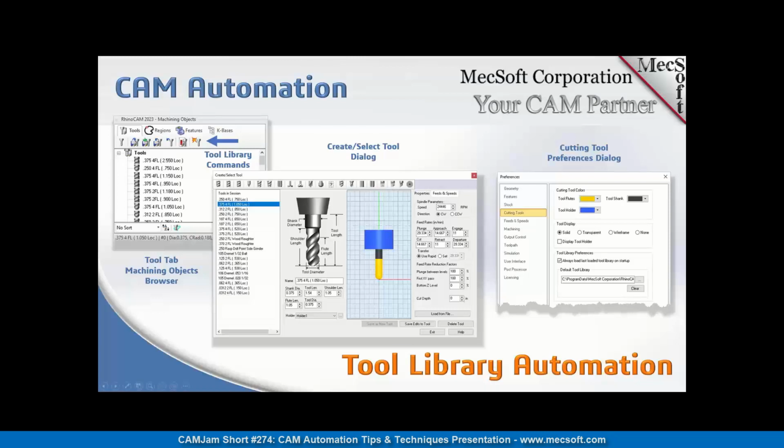When you define your tool, you're obviously going to set your tool dimensions, and you can set your feeds and speeds and the properties of the tool and some other options here. This knowledge gets saved with that tool based on the tool name. So you can embed all this knowledge that you need for a certain tool, and then you can carry that knowledge over into your operations when you load that tool.